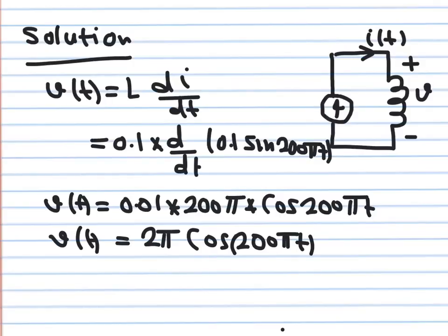This means that the voltage leads the current, as we explained before in the case of the capacitor. In the capacitor case, I mentioned to you that the current leads the voltage. Here there is also a lead-lag relationship between the inductor current and voltage. You see the voltage is a cosine. This means that the current is a sine. And as we agreed from the case of the capacitor, the cosine function is ahead of the sine function.